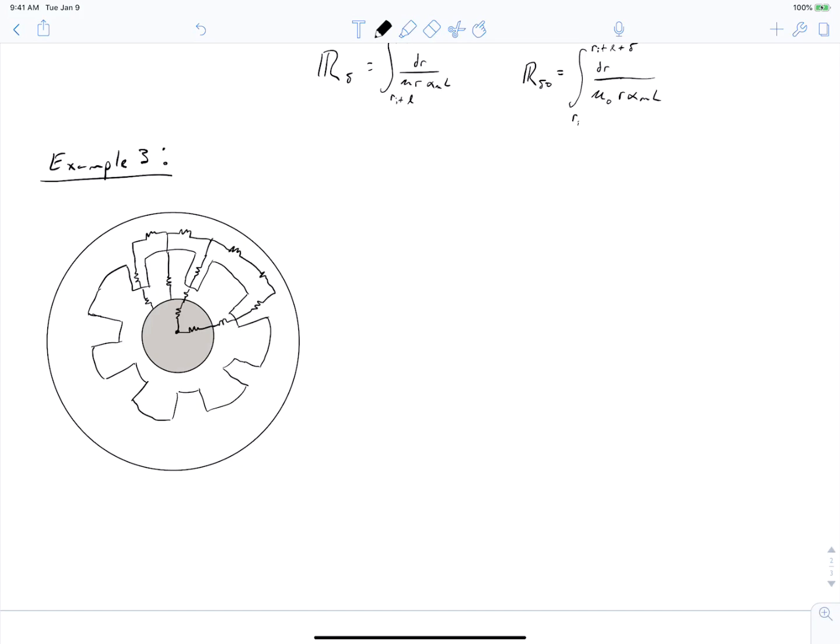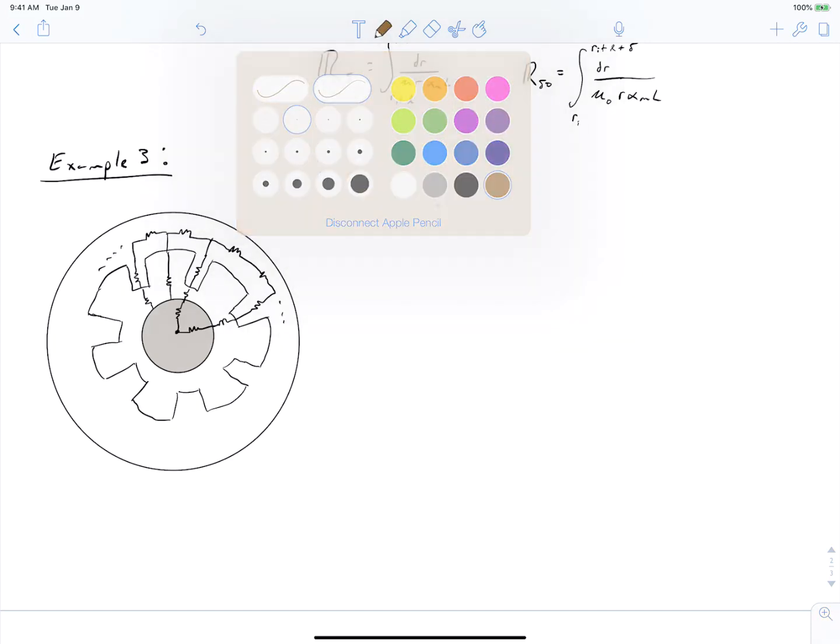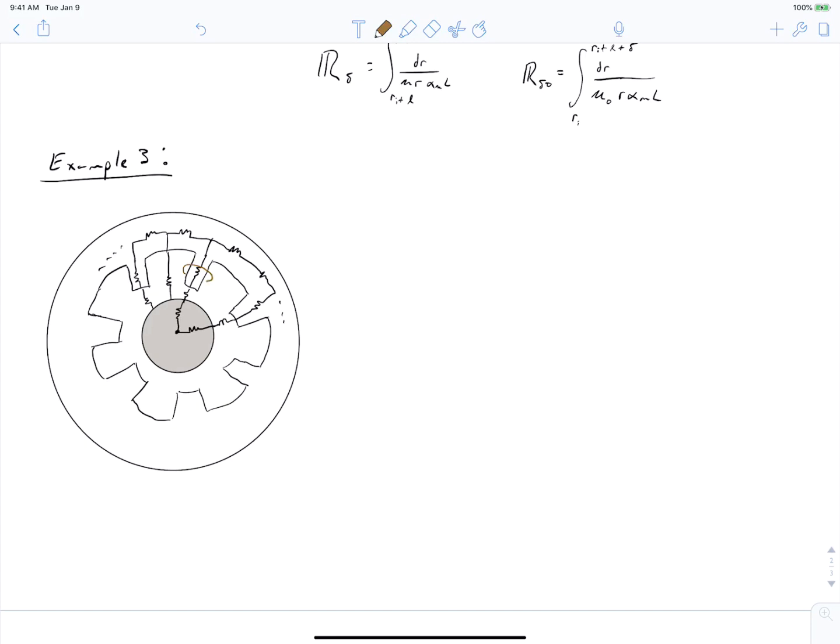And then in the stator yoke, you'd have some reluctance network like this. And so you can kind of get the idea here that we'd fill this whole thing up with an elaborate magnetic equivalent circuit. And if we model our windings as well, if we have a coil that wraps around this tooth, and a coil that wraps around this tooth, and so on, we would add in current linkage sources to our equivalent circuit. And so ultimately we could solve this complex set of reluctances, this reluctance network, to get our field everywhere. And depending on our rotor structure, we might have some kind of tooth shape in our rotor that as it rotates we'd be connecting and disconnecting different reluctance paths to the stator, and our various current linkage sources would be excited based on what the phase windings, the three-phase windings of the motor are doing.